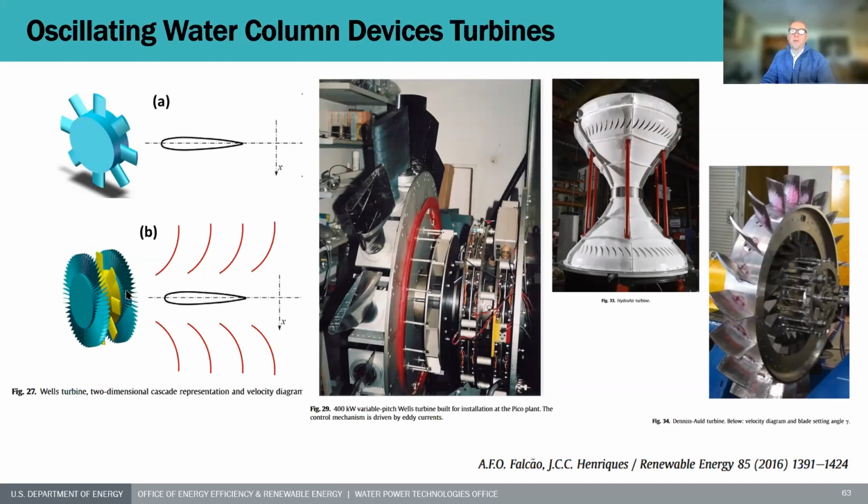Another arrangement with guide vanes is when you replace this Wells turbine and you have much more curved guide vanes and also very curved blades on the rotor, so that you could say that the force application on the rotor primarily comes through momentum directional change.